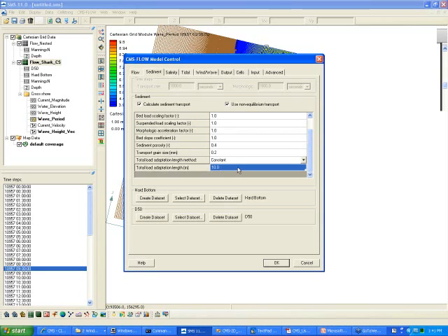If I realize that the results are not sensitive to that parameter, then I'll just leave it. If I realize it is sensitive, then I'll do more tests and try different options. I'll set up a script to set up multiple cases, maybe 10, 15 cases, and then try them all, simulating short periods of time.